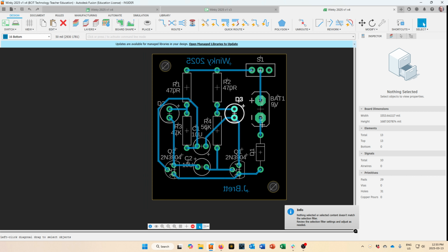This board that I've done, I could make it a little bit smaller and compact everything in. It would make it less expensive to produce with a group of grade 8s or grade 9 students, but maybe it's nice to have that little bit of extra space to give them something bigger to work with. Certainly, the smaller you can make it, the less expensive it's going to be because you'll be using less printed circuit board material and having to etch less copper off.